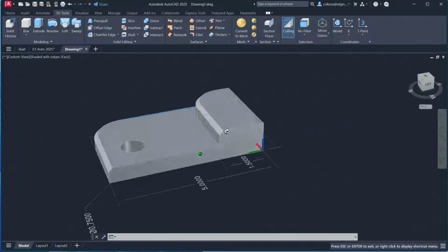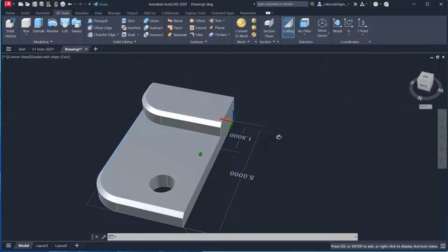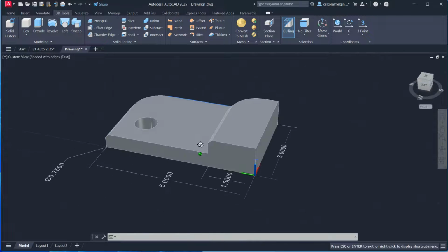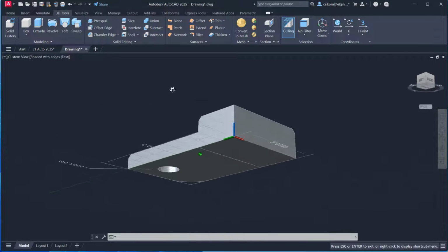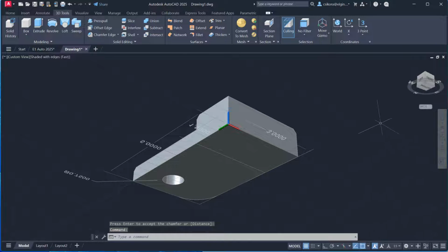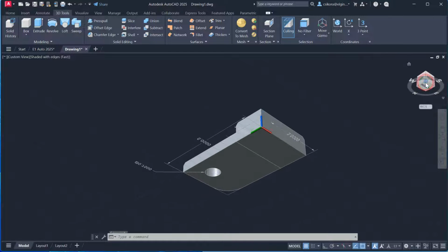Hold shift and drag and you could rotate this around and see the geometry. And I'm saying drag with the middle wheel like we learned earlier. So go ahead and rotate this so it looks like this. Basically it's the bottom cube between left, front, and bottom here. You could click on that and that will give you exactly the same view.